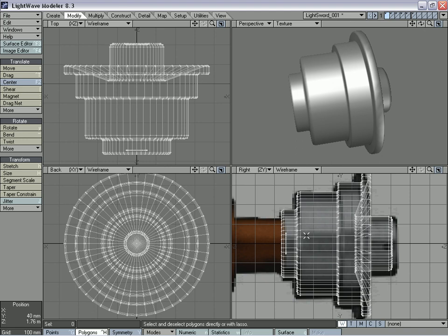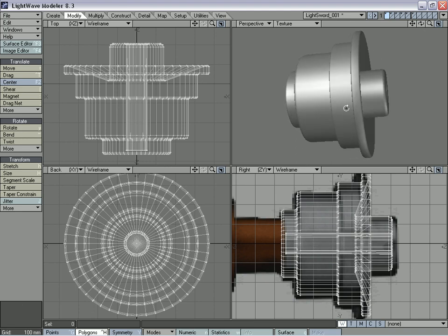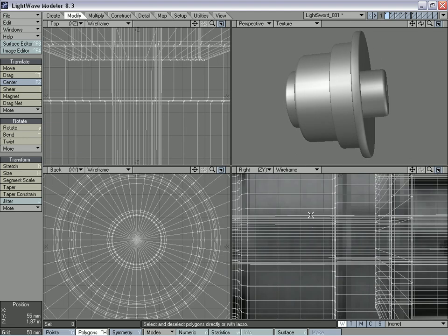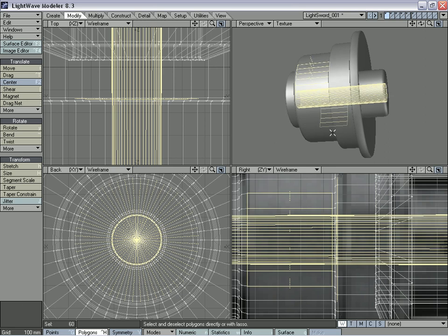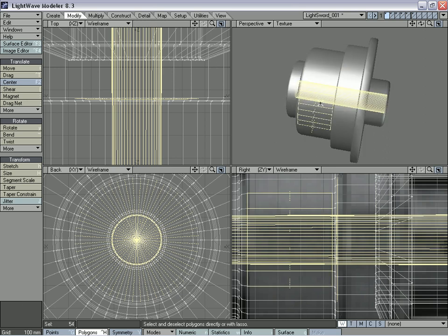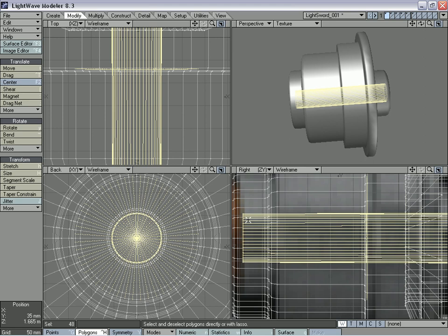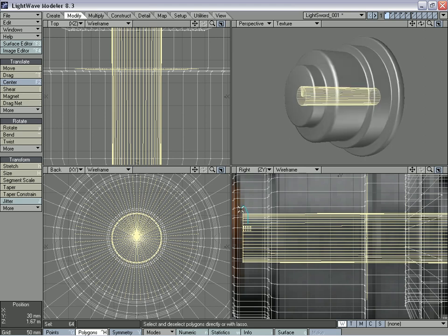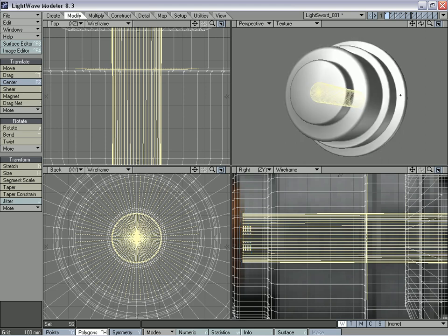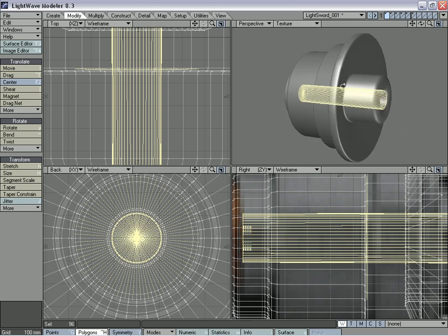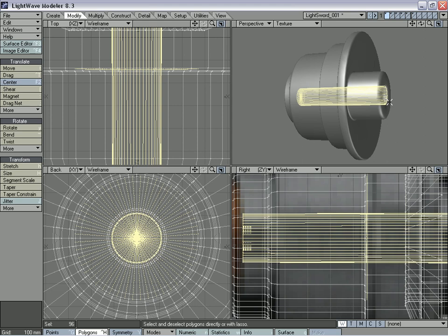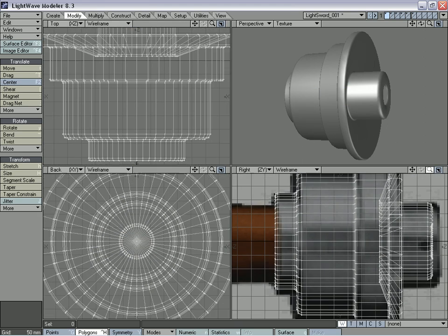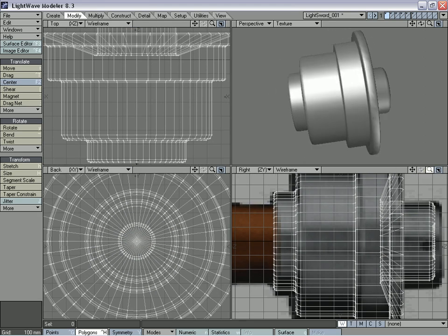So to show them again, use the backslash key, which is right above enter or return. And we're going to reselect those again, and then also go through and select this cap, which we can lasso to make sure we get them all, holding down shift so that we're continuously selecting and not deselecting. Then hit the minus key again, and that will hide everything we don't want cut.